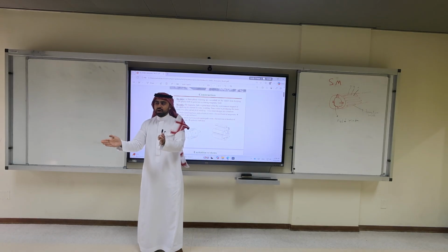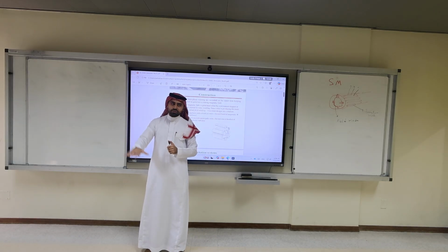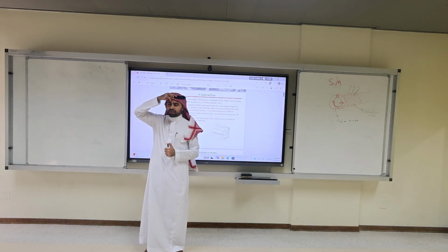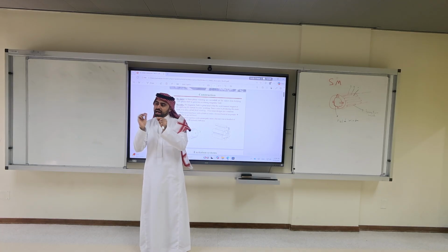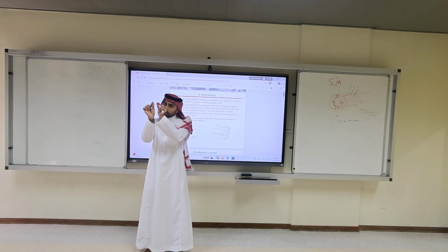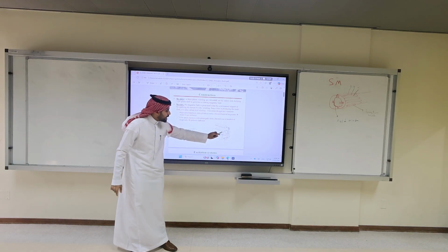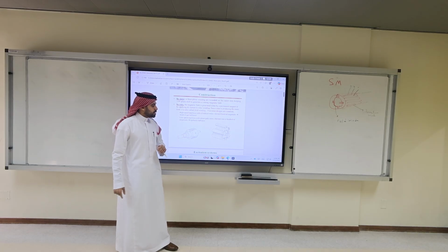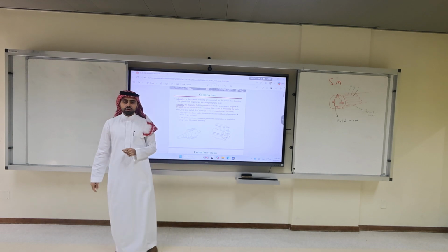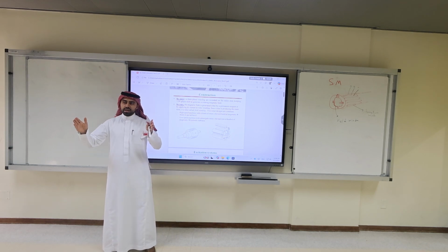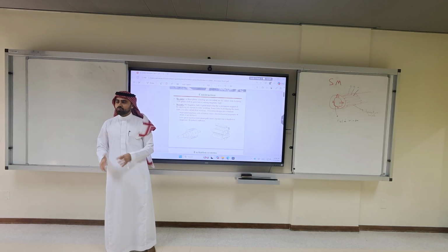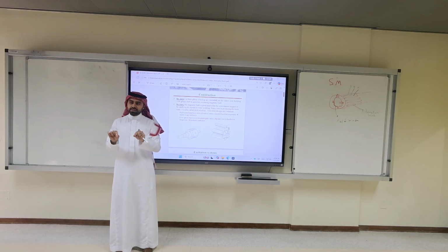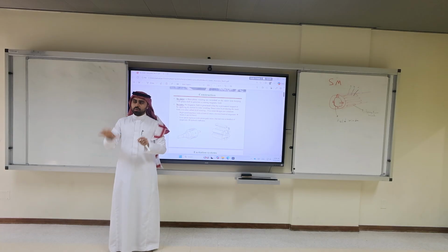Get it? Now, there is a whole course that's not offered in KFUPM, but it's usually offered in graduate programs in some universities, where they teach how to design these windings. What is the optimal size of the slot, for example? Where to put the magnets? How many poles? It turns out you can't put whatever number of poles you want. There are standards that govern the harmonics generated from whatever you put. For example, how many slots in the stator versus how many slots in the rotor. There is a strict combination.